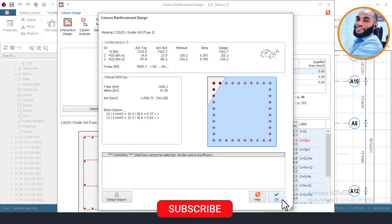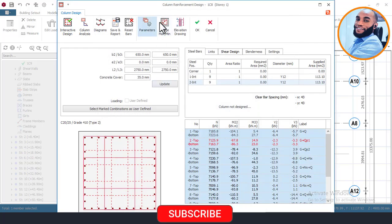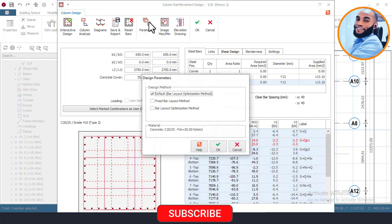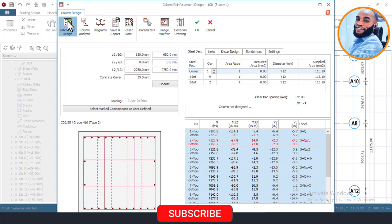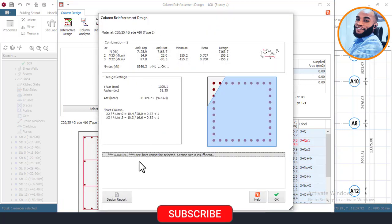Now, on this place, I'll have to come here and check. Now, there's sometimes that you're going to click here. So I'll click here right now and change this design method to fixed bar layout method, and then come here and click okay here, and then design again, and check again if that will be okay. Let me see. It's not okay.